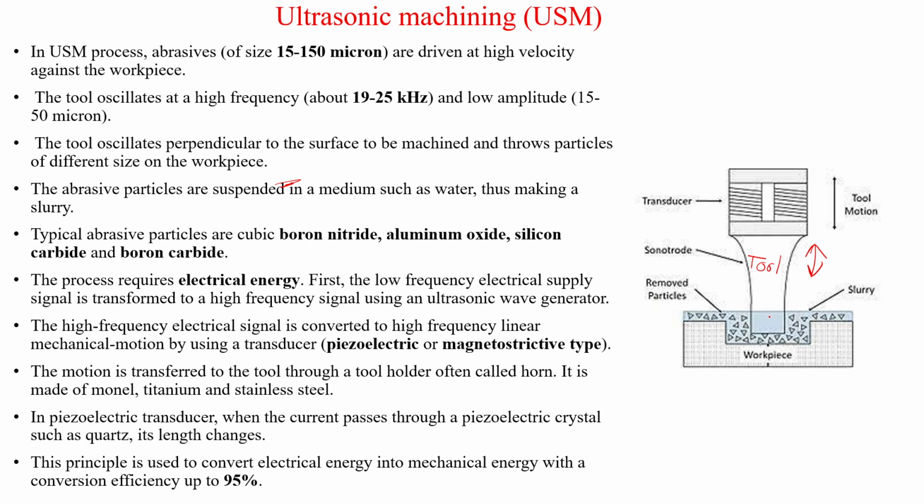Because of that, the slurry has an impact force. Basically, it is governed by some impact force. So when the tool strikes the slurry, it pushes on the workpiece with some impact force. Because of that, the particles of the workpiece start plastically deforming.